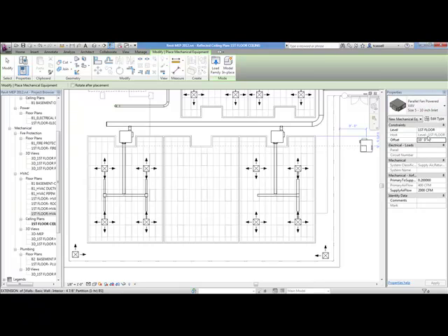Minor difference. The big difference between Revit and AutoCAD is the fact that you now have to worry about one extra thing, and that's a 3D value. A lot of people think that I don't need 3D. 3D is just going to get in the way. It takes too long. None of that's true. You're going to find that 3D, as we mentioned earlier, is going to help with your coordination, and it really only takes one extra field to fill out, such as a 10 foot 7 inch elevation, and then place the block.